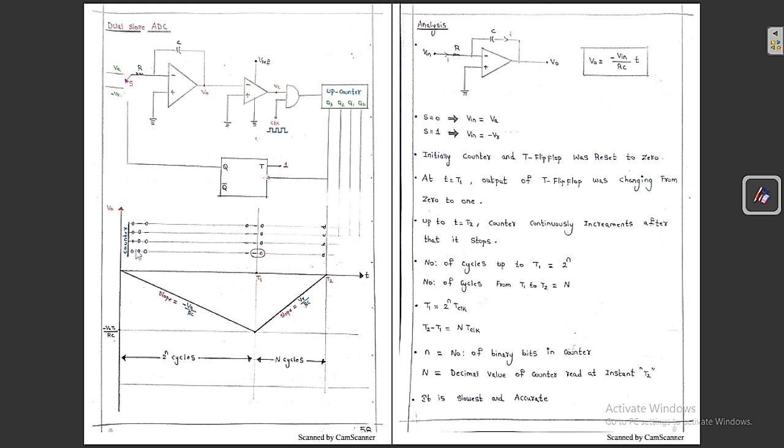This is the counter which goes 0000, 0001, 0010. So it is going to count here. See, finally you are going to get 1111. Up to here it is going to count like this. Then you are going to get the initial point again, 0000. Whenever 0000 comes, you can see clearly that Q3 is changing from 1 to 0, which means negative edge triggering has occurred.